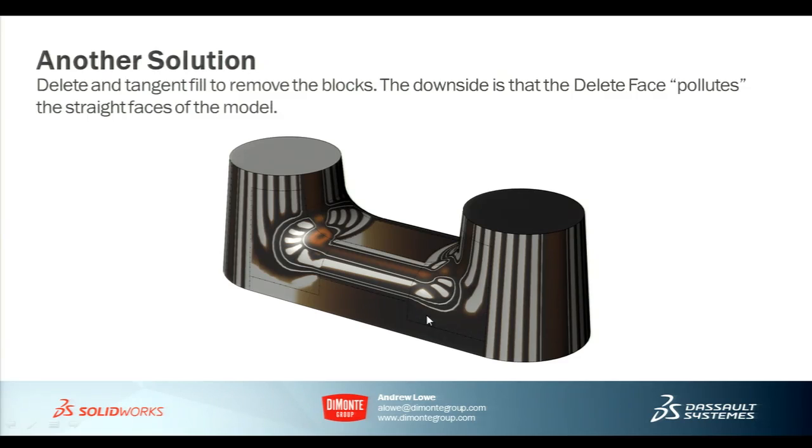So this technique is actually more stable because you're relying on blocks that are extruded in the model and not making sketch relations to vertices in the model. However, you need to be careful and dial in the size of those blocks to get them as small as possible so you don't have the potential of polluting your nice clean faces on the model with blend faces.